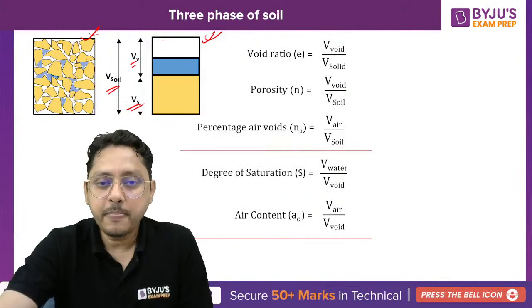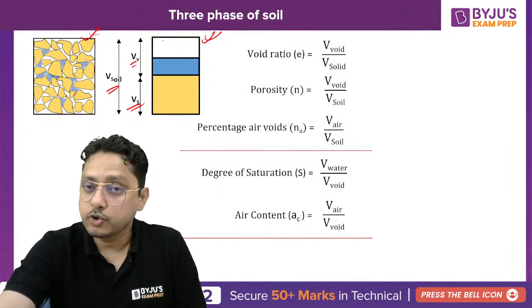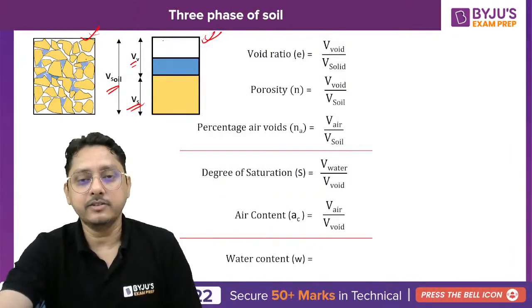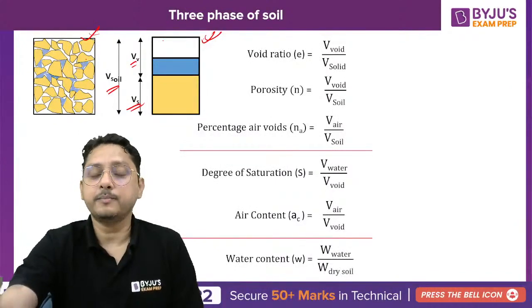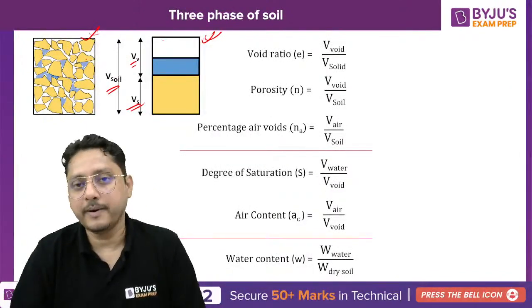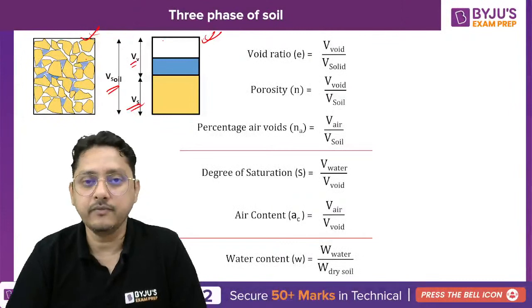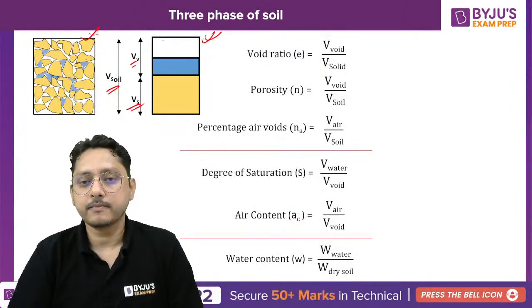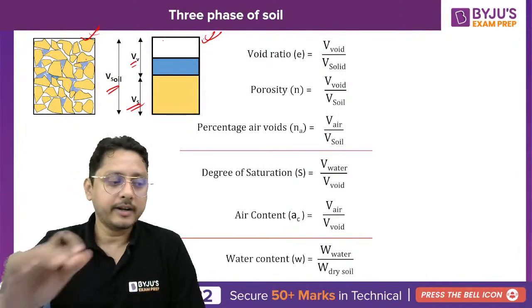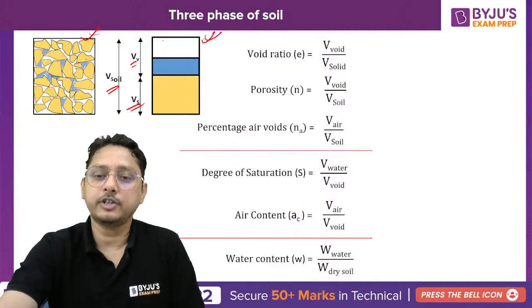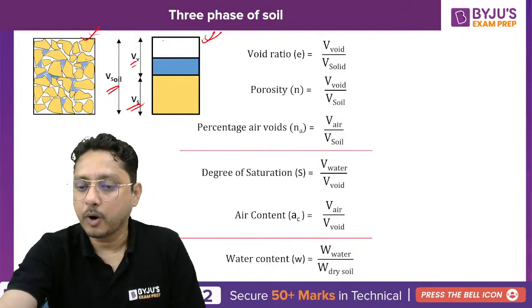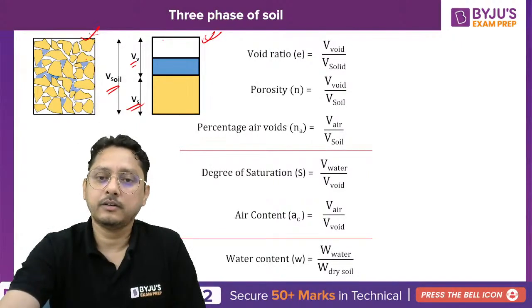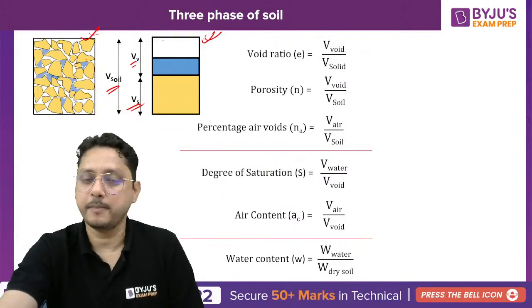Then one more thing: do not get confused between the degree of saturation and the water content. Water content is with respect to weight. It is nothing but the weight of the water present in the soil mass with respect to the dry weight of the soil. The water content is weight of water with respect to dry weight of soil. These are a few important definitions which you have to remember.